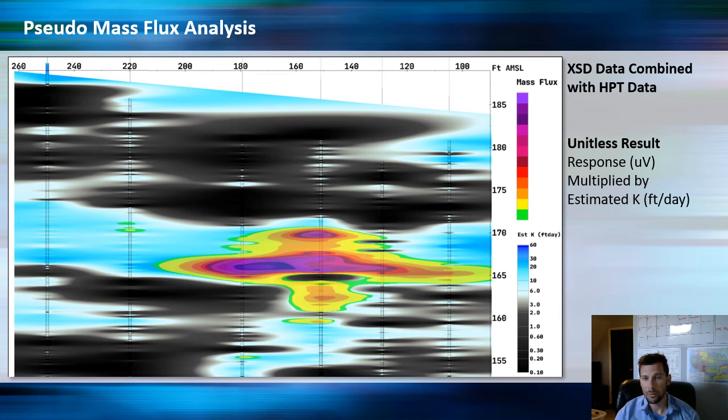But I think it's still really interesting to see that maybe in the area to the left there's more mass moving through there because the groundwater is moving faster. So if we wanted to target a remedial technology, like a slurry wall or a pump and treat system, we might want to not only be concerned about that one area, but also the area to the left there and get that whole plume.